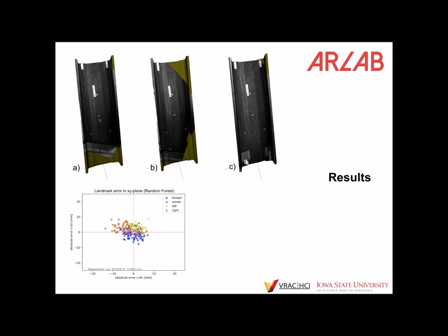The landmarks are here a hole, and there are here some artificial landmarks, this grayer zone. I hope you can see them here. This light gray zone, and with our tracking technique and the calibration techniques that we use here, we can get this to ±10 millimeter, most of the time even better. The spread is a little bit high, but that's good enough to find delaminations on those parts and to identify them nicely. We did the same thing for ultrasonic tracking, also first on a small scale.